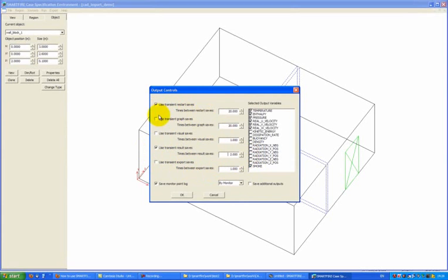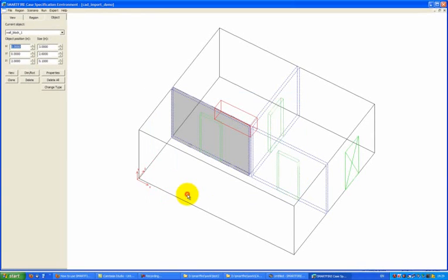If I have concerns about the stability of the simulation, it's also worth saving the restarts more regularly in case I find that things crash, go numerically unstable, because I might need to control them and change them. In this case, actually being able to restart and change the control settings could be very beneficial. So once everything has been activated that you need activated and the frequency of saves is prescribed, you can then select these settings.